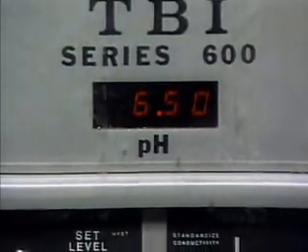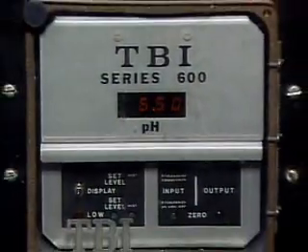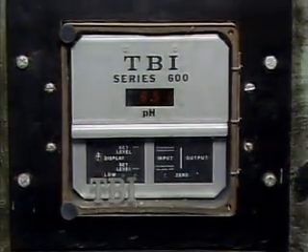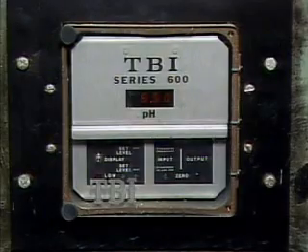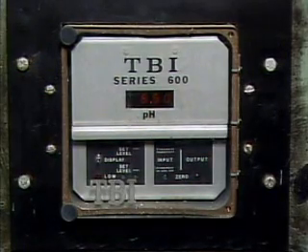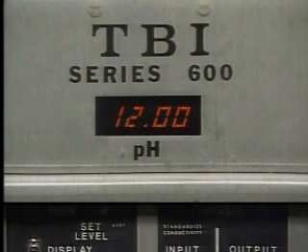A relatively low pH tends to increase the likelihood of corrosion, while a relatively high pH tends to increase the likelihood of scale formation. If the water's pH is high, acids such as sulfuric acid, which have a low pH, can be added to lower the water's pH. On the other hand, if the pH is too low, an alkali is added to raise the water's pH.